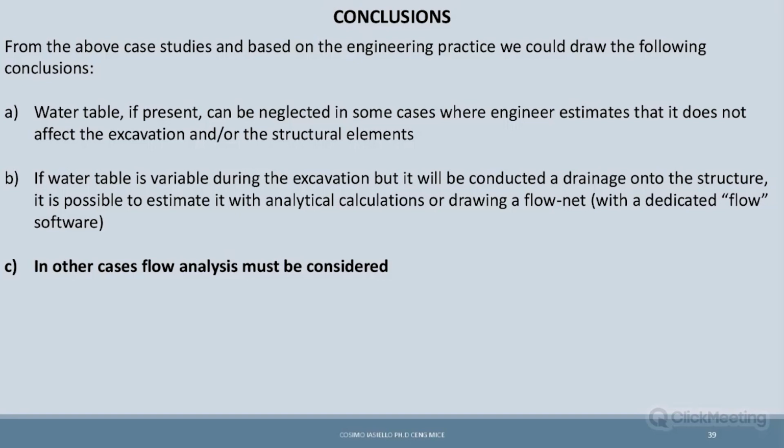If the water table is variable during the excavation, but drainage will be conducted onto the structure, it is possible to estimate it with analytical calculation or by drawing a flow net. This is something that actually should be done all the time.